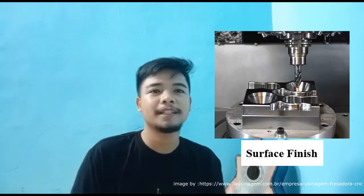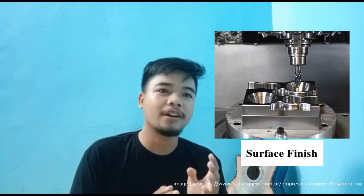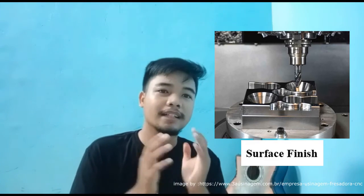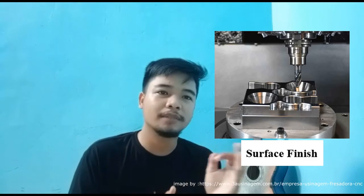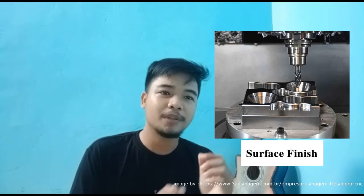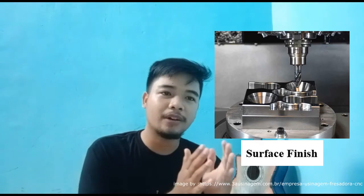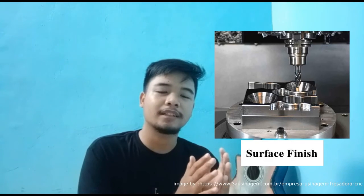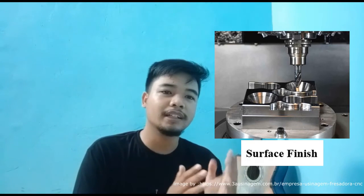2. Surface finish. Any material put through the cutting area of the milling machine gets cut at regular intervals. The side cutters have got regular ridges on them. The distance between the ridges depends on the feed rate, the diameter of the cutter, and the quantity of cutting surfaces. This can cause significant variation in the height of the surface.